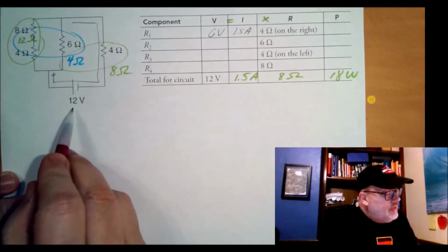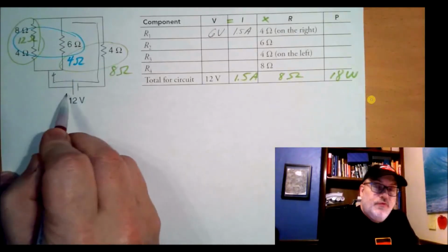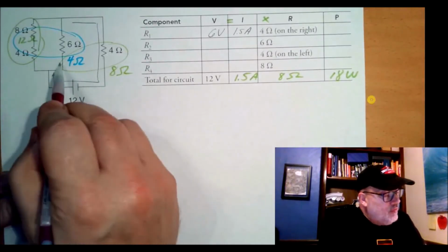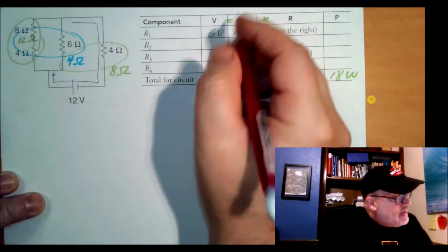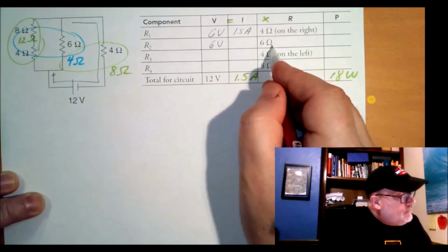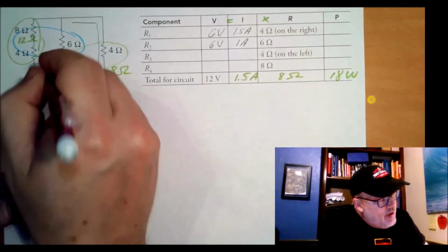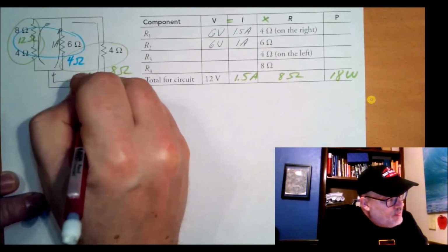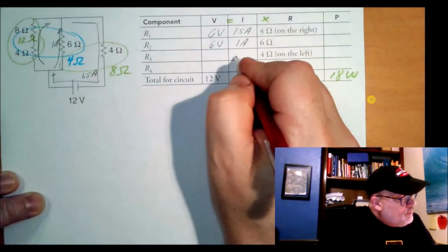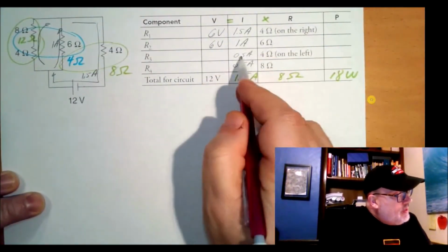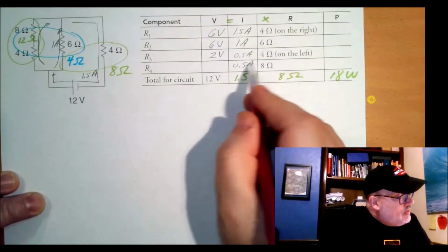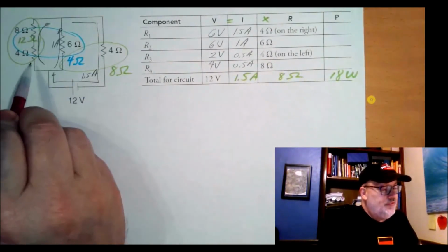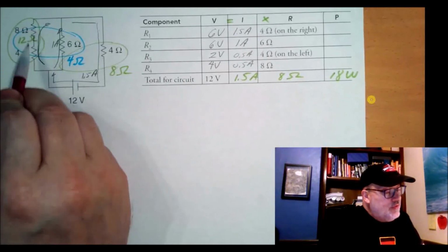That leaves, what, 6 volts left, because this is consuming 6, this is providing 12, so I have 6 volts left. And if we go around this loop right here, we can see that that's plus 12 minus something minus 6. So this has got to be 6 volts for this one. And since it's a 1 ohm resistor, that's 1 amp. All right, and now we can see that this has to have 1 amp here, and this around here has to have what's left. This was 1.5 amps, so that means going through these two must be 0.5 amps each. And then we can multiply these two, so that would be 2 volts here, and that would be 4 volts here, which makes total sense because the voltage across these two has to equal this one. This is 6 volts, and so that is, what do we get? 4 for this one and 2 for that one, which is 6.